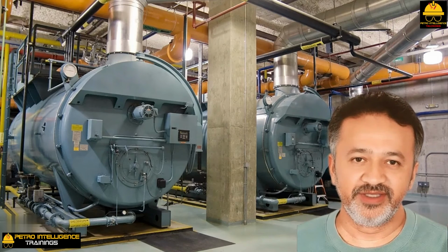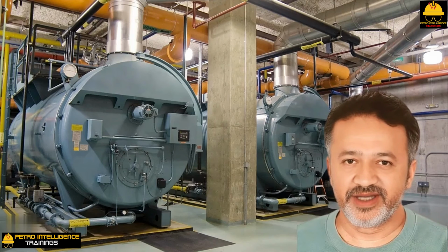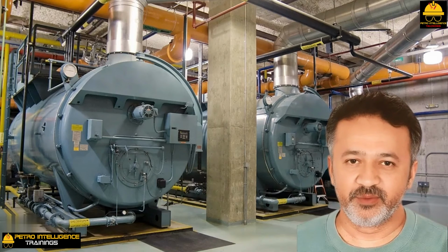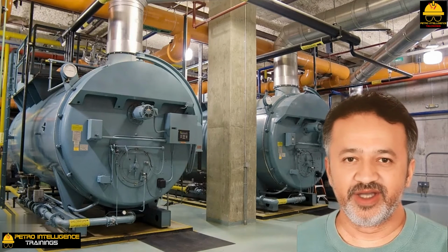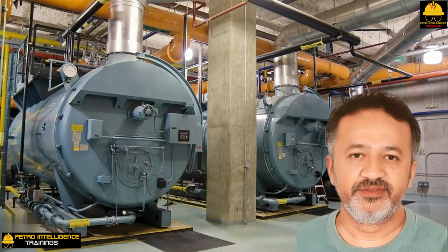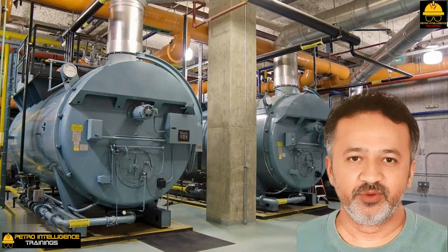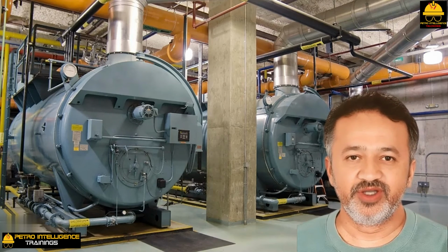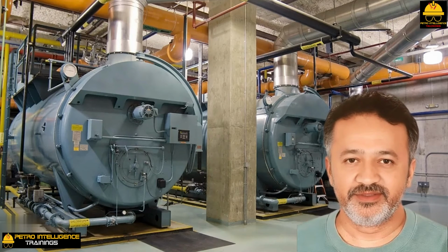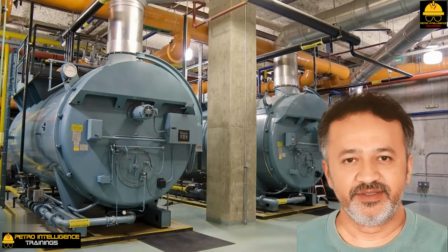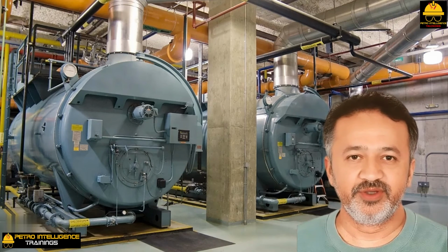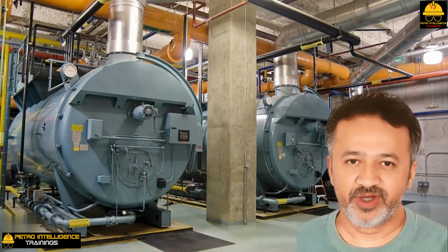There was an accurate oxygen analyzer on the flue gas stack. It typically recorded several % oxygen in the boiler stack. However, this O2 value was ignored, and correctly so, by the operators. They simply adjusted the fuel gas rate, which had a variable heating value, to maximize steam production with a fixed amount of combustion air. If, on the other hand, they had been trying to produce a fixed amount of steam, then they would have adjusted the airflow to minimize fuel gas consumption in the boiler.